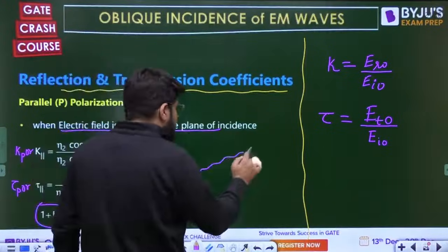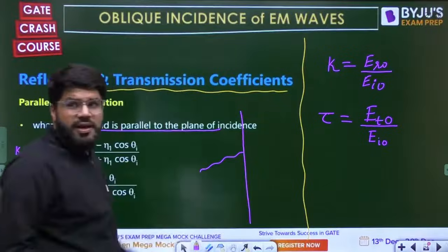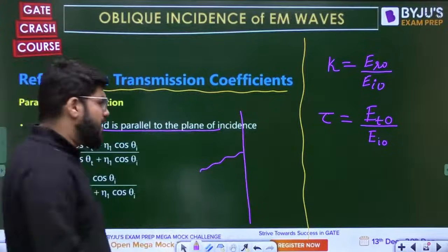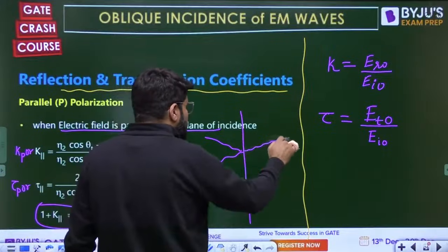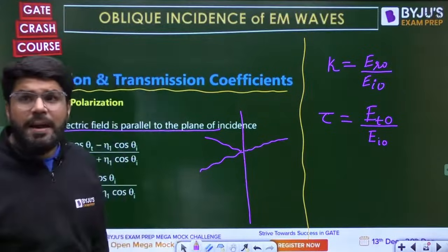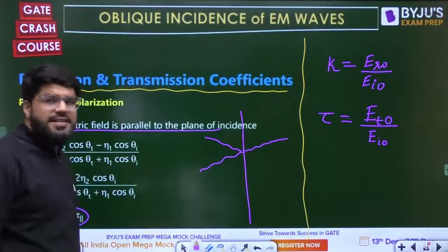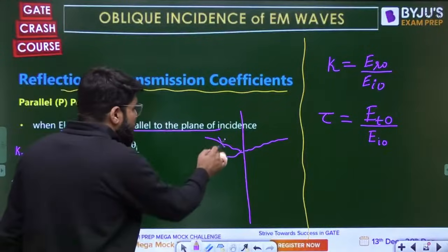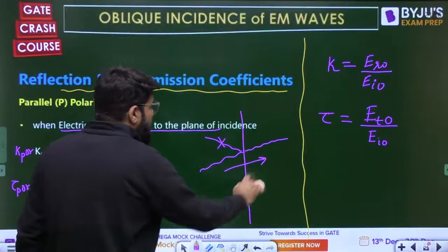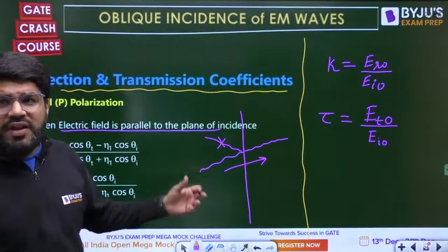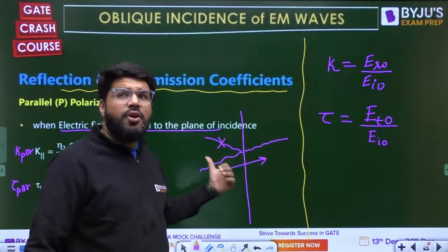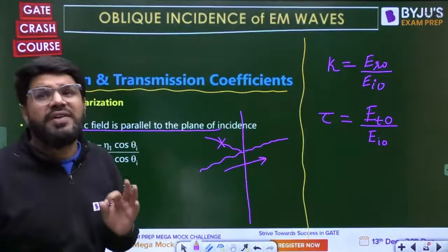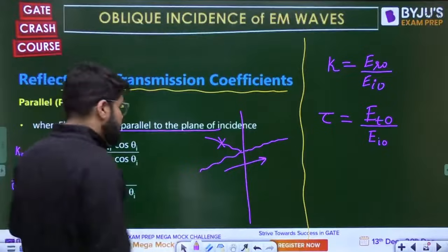You have transmitted information, it met a boundary, a discontinuity, and usually a portion of it bounces back and only a specific portion is propagated forward. But if you ensure that k is equal to 0, then there is no reflection, and whatever wave you have sent is going to be transmitted forward fully, without any loss. That is what we ideally want.